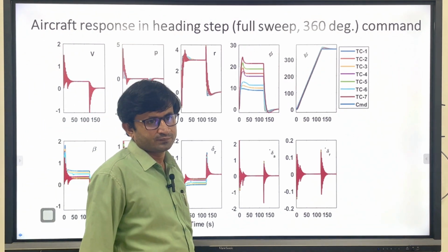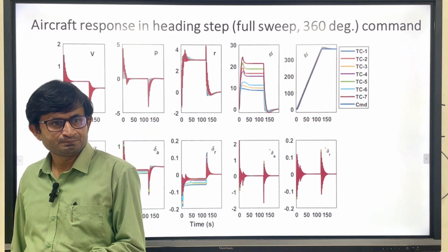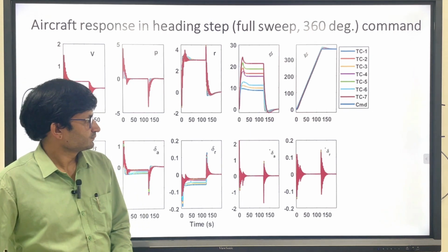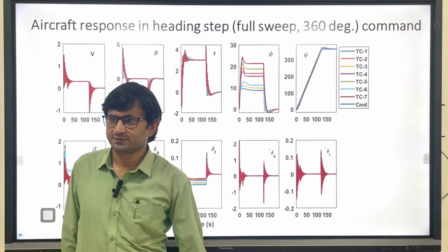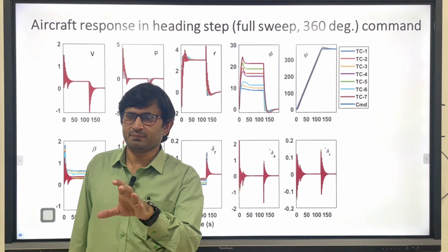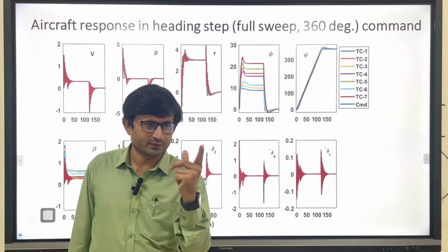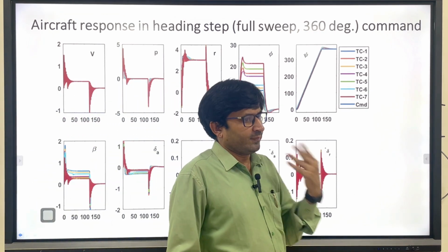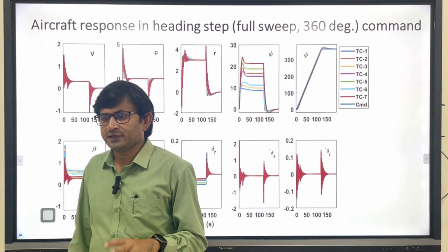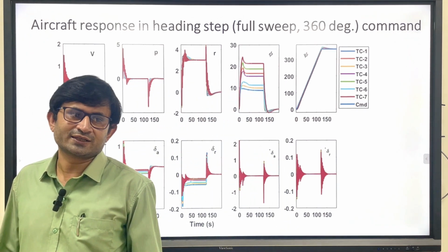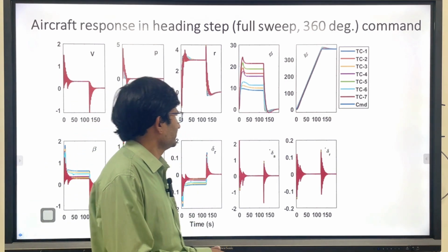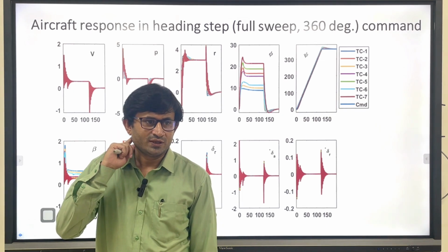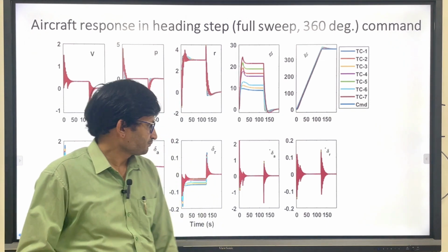So that is how you achieve the perfect turn. But what is the major control, the main control required in order to make the turn? Aileron, right? The dominant motion you can achieve using this, but in order to make it perfect, you have to use the other controls also. So we have seen that in a perfect, coordinated turn, all 4 controls are required.